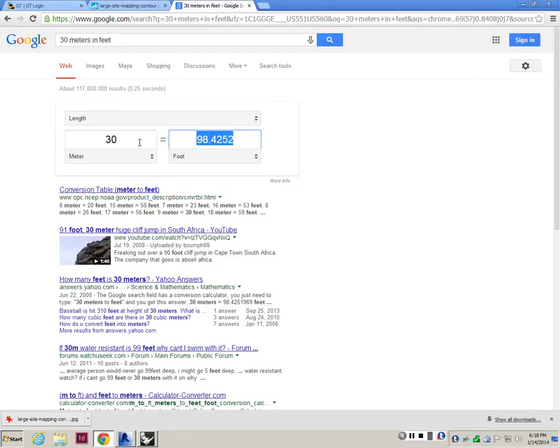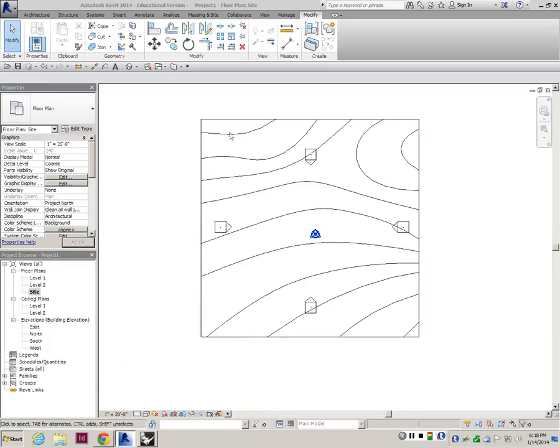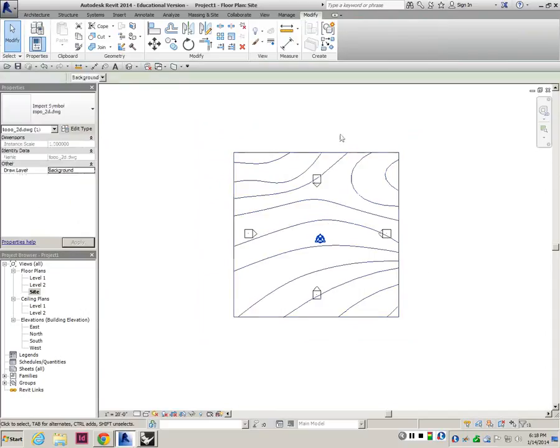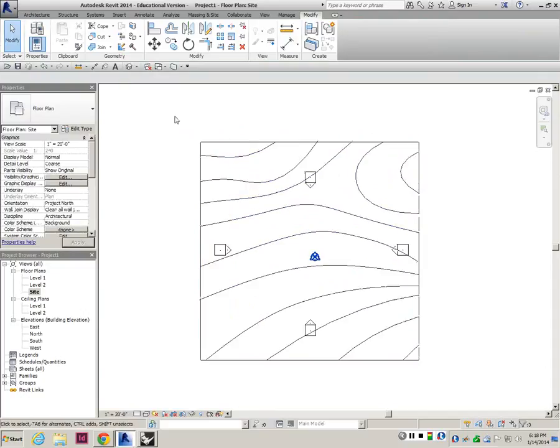That will be 1/5. 20% is slope. So for 40 feet we have 1, 2, 3, 4, 5, 6, 7, 8, 9, 10. We have 10 lines, so each contour would represent 4 feet, right? So let's think about that and start modeling a landscape.